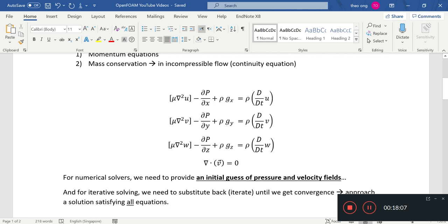If the divergence of the velocity is 0 everywhere, then it satisfies the continuity equation and solves it. But if it does not, then we have no idea what the next guess of the pressure field is. You'll have to guess a million kinds of pressure fields or many different combinations, so it's just guessing and checking.